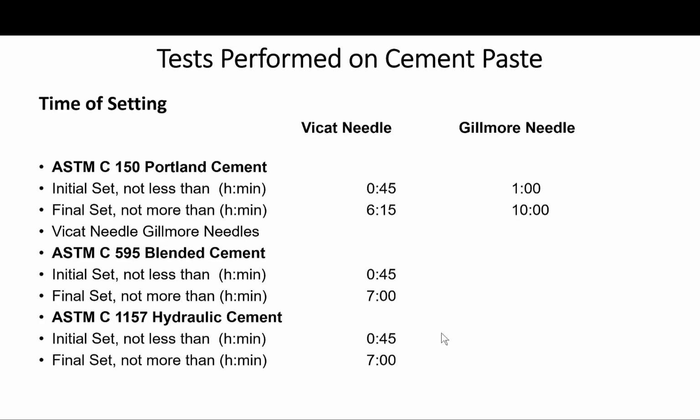Okay, here are shown the setting times for various cements using the Vicat needle and the Gilmore needle. The Gilmore times tend to be longer than the Vicat times. Recent research has shown that setting times determined by the Vicat needle correspond closely to significant changes in the fluid properties of the paste. A modified version of the Vicat test can be used to determine the setting time of mortars according to ASTM C807 also.